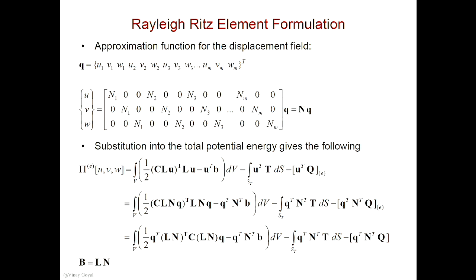So let's take the example of a tetrahedron. How many nodes do you have for a tetrahedron? You have 4 nodes, right? In 3D. I'll show you a picture later. So how many degrees of freedom do you have? 12. So one element has 12. So your stiffness matrix has to be 12 by 12. We're not giving you that in the file, because you'll spend more time writing these matrices than doing the work, as you're experiencing right now for the heat transfer problem. Sorry, you have to go through the pain once. You don't have to do it again.